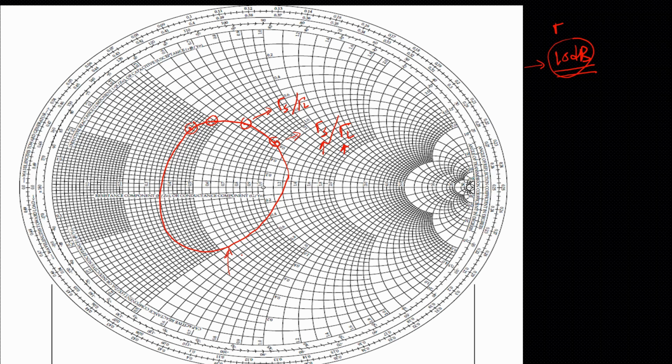and after designing with those gamma S and gamma L, if I get the same gain which I had specified, then our work will be simple, because we have some way to go from gain to gamma S or gamma L. Because from gain we can't directly make our circuit, we need the values of gamma S and gamma L. And this technique which we will derive today is called the unilateral constant gain circle.